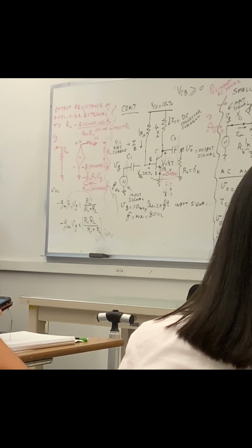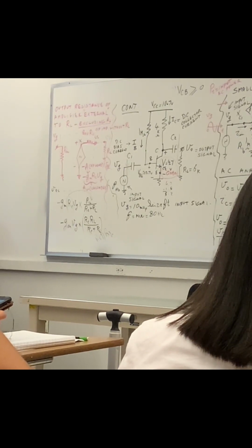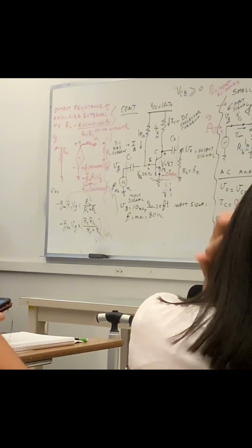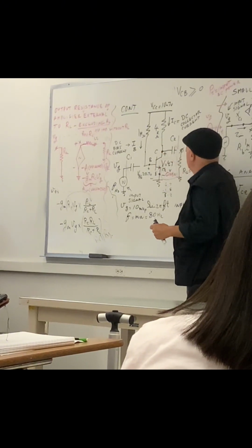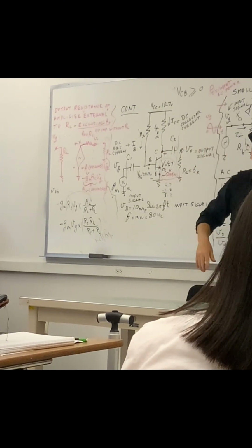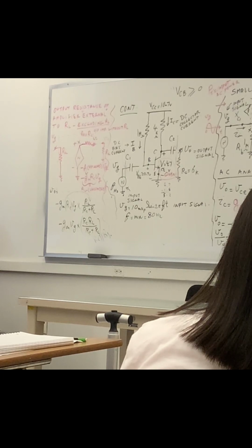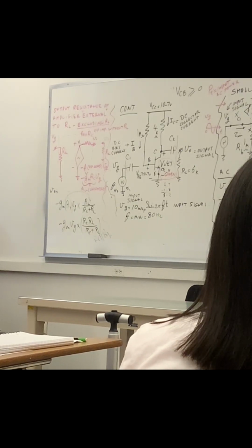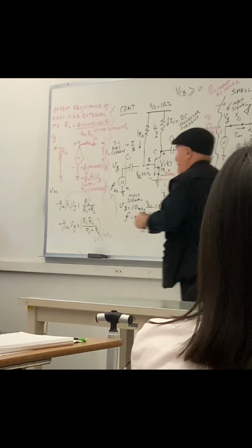We can't afford that in sound systems, because your load in the sound system is a 4 ohm speaker. It's a killer, will bring voltage gain to nothing, basically. So you need some kind of a final stage when it goes out with a very, very low output impedance. Maybe an output impedance of 0.1. It can be done. An output impedance can be designed to be very, very low. Okay, this is set. Now, let me see how much time I have.